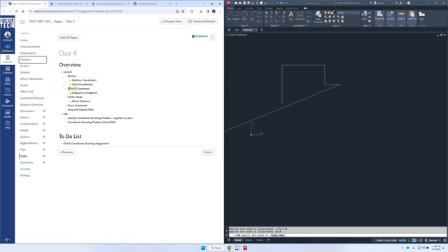A few new things we're going to learn today, right? To add on to our knowledge, to increase our experience in AutoCAD, we need to learn about object snaps. So that's what this OSnap command is. And the first object snap that we're going to learn is the endpoint snap. So let's say on this drawing, if I hit escape or I'm not connected to that point, well, if I don't have my snaps on, unless I know what that coordinate is, I can't reconnect to that point.